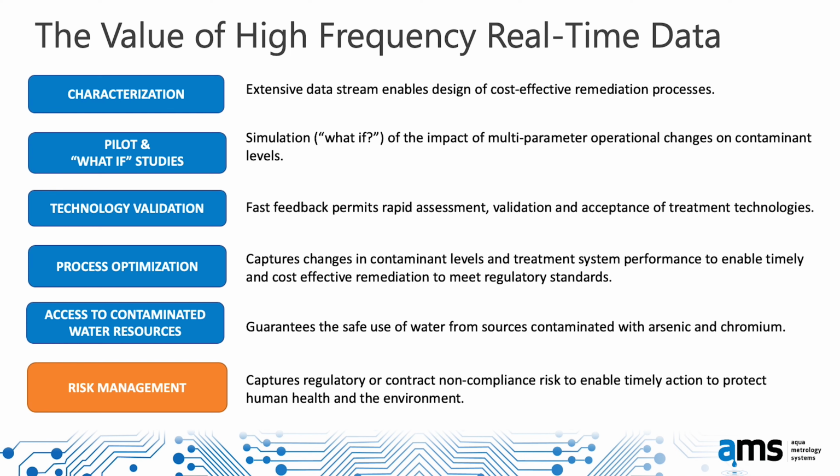There's not time to go into all the applications for online real-time water quality data that go beyond the obvious: process control and risk management. Suffice to say, online analyzers are being used by utilities and engineers to address a wide range of challenges, from characterizing contaminant levels across a water treatment system before designing an upgrade or a new system, to validating new treatment technologies. Water blending is also a major application for real-time data, where utilities are able to now blend water from contaminated wells with water from higher quality sources to still produce a blend that is safe to consume.